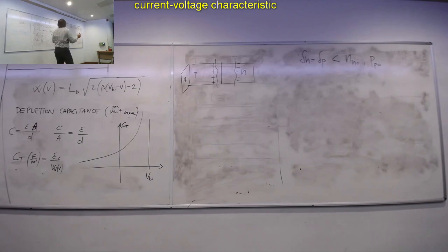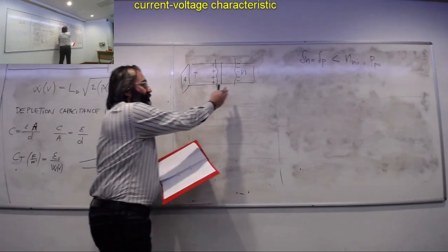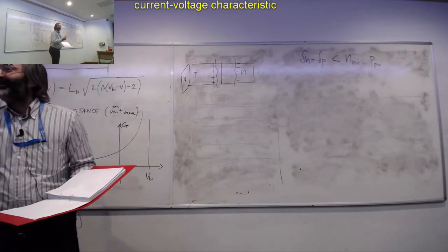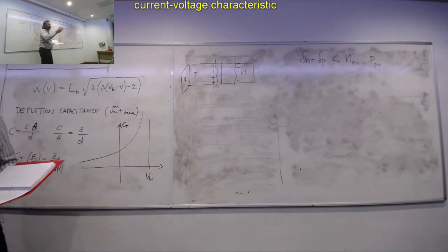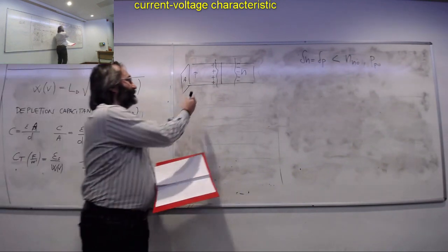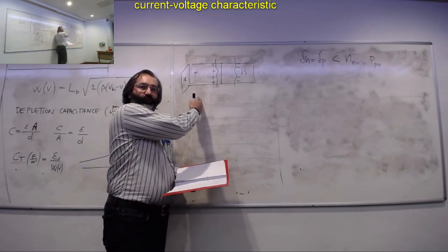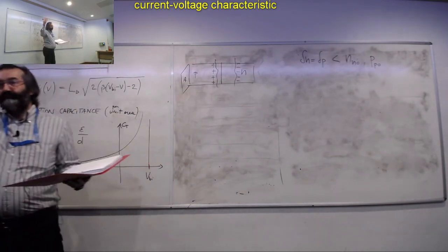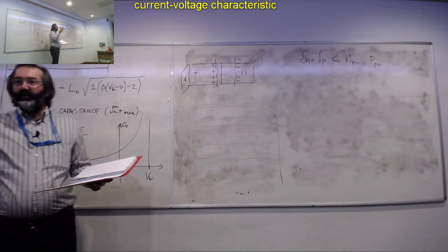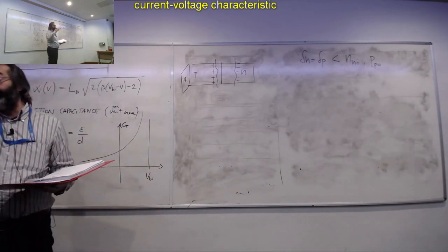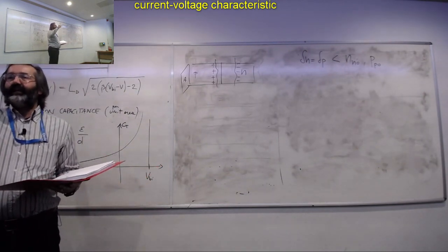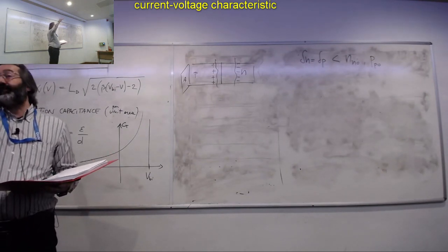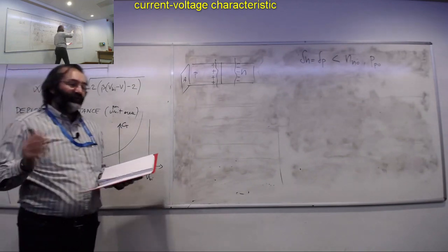And finally, the semiconductors we're dealing with are non-degenerate. You remember what it means? It means that the density of electrons and holes is not extremely high. In terms of the energy diagram, it means that the Fermi level is at least 3 kT from either the conduction band or the valence band. Go back, have a look.